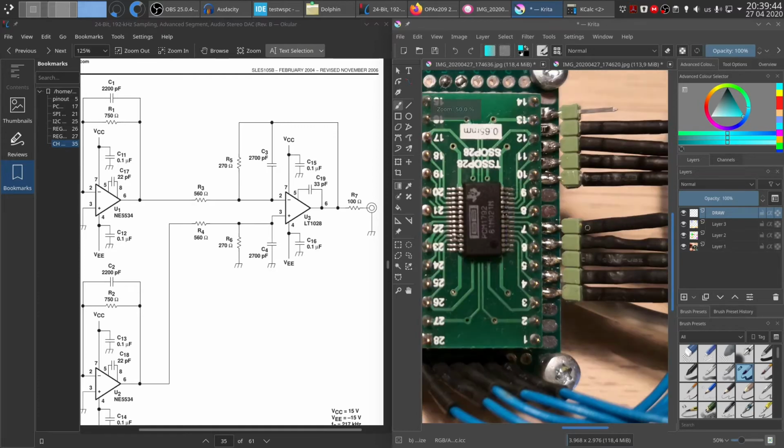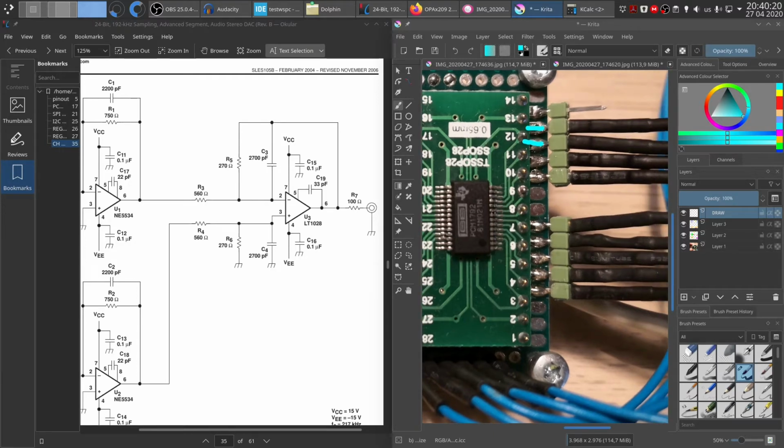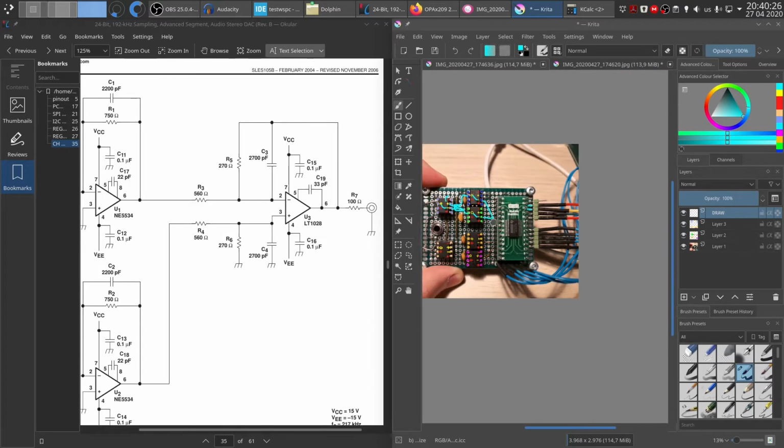One thing again, the digital portion over here doesn't have really much. It has only the SPI and the I2S over here, and a few pull-ups and supply pins. Also, as you can see, there are a few resistors, and there are 100 ohm resistors connecting the actual wires that are going to the microcontroller and the pin. This is just so if I happen to short these wires when I'm testing and they're just flying around, they don't short anything important and fry the IC, because it is an expensive IC going from 12 to 14 euros, so it's not really the safe way to do it. So therefore I just used some 100 ohm series resistors to terminate the inputs. Okay, so this is hardware taken care of.